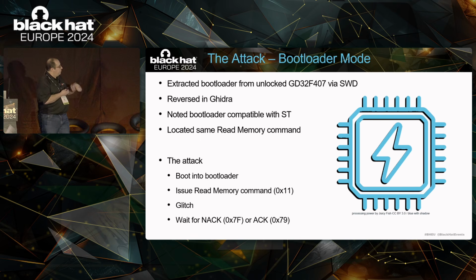So the attack was to boot into the bootloader, issue the read memory command, perform our fault injection, and then wait for a NACK or an ACK, in this case a hex 79, to affirm that we could access the firmware.